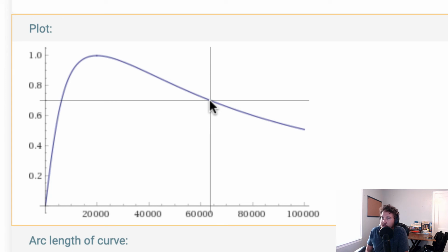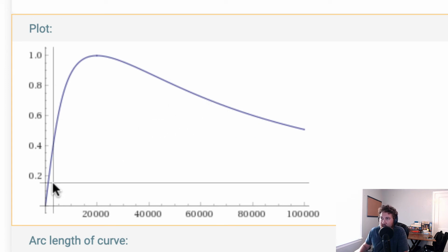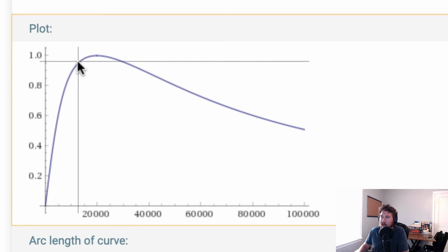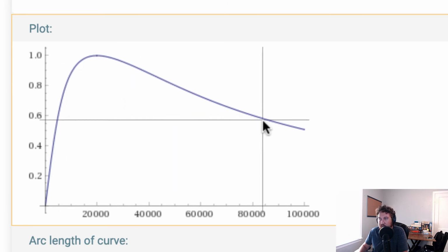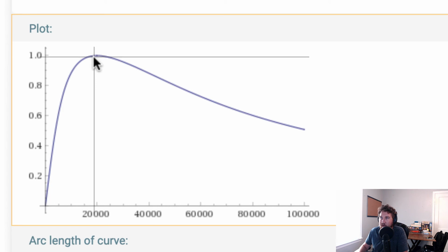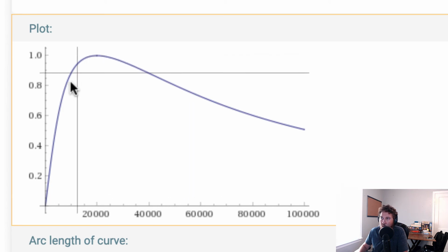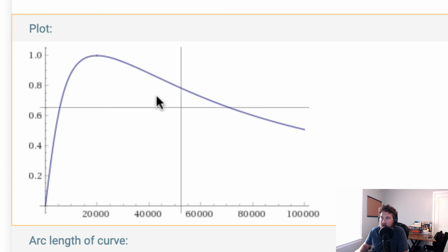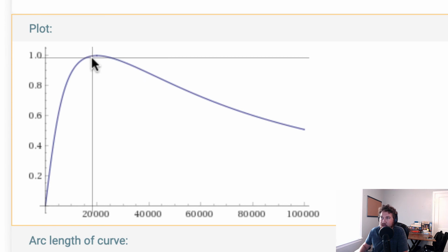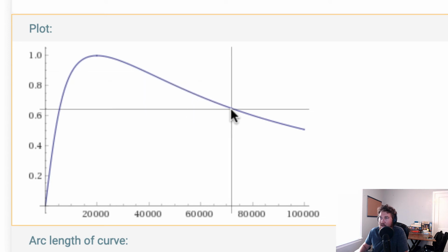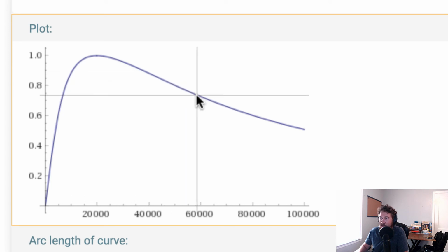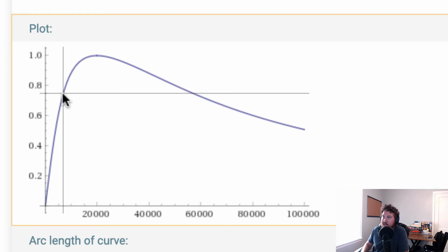That looks pretty good. So yeah, you can see that it's not that ideal sort of rectangular curve. It does this kind of weird sort of high peak and then tapers off. And this is kind of why we said that passive filters aren't that clean or don't have that much quality factor to them, because they still let an awful lot of bandwidth get in there. So the bandwidth on this guy is pretty huge. But that's a good looking filter, and that seems to work out just fine.